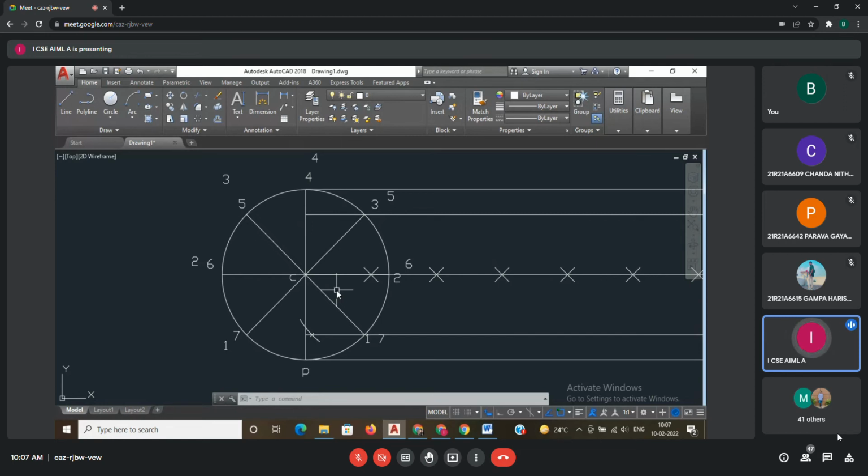Now here it is clockwise. If I say anti-clockwise, definitely you will get some confusion. That's why follow one procedure. Whenever the rolling circle rolls clockwise, you have to take notations anti-clockwise. The rolling circle rolls anti-clockwise, you have to take clockwise notations. That's it. But in a cycloid case, you won't get difference. But in epicycloid and hypocycloid, you will get the difference.